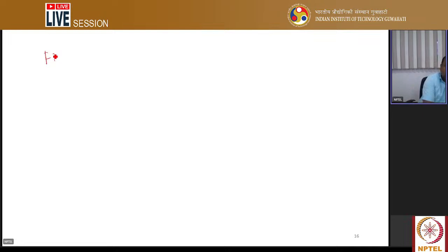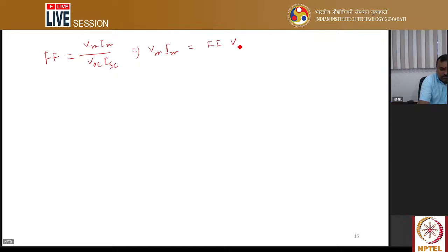Fill factor, if we write, it is FF = (Vm × Im) / (Voc × Isc). That means Vm × Im = FF × Voc × Isc, right?